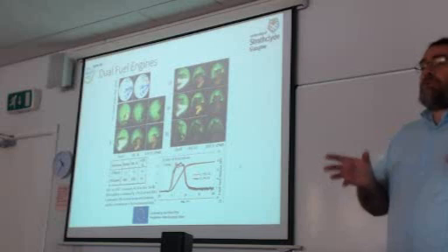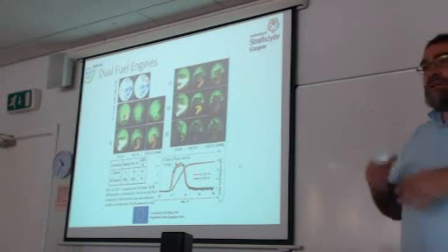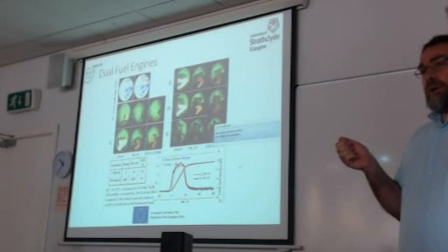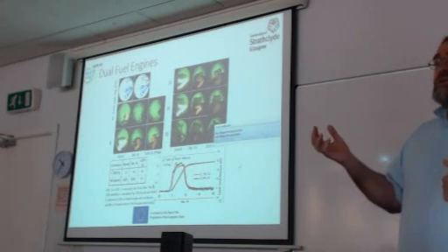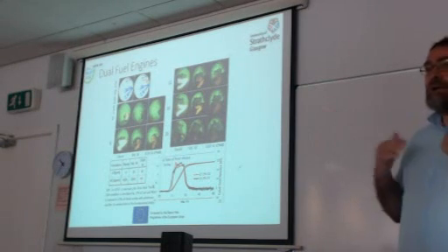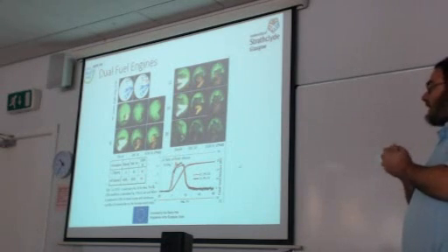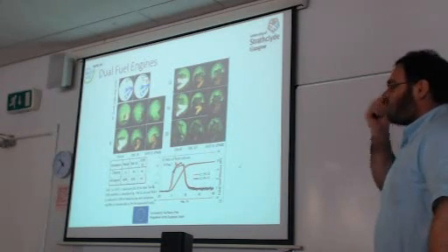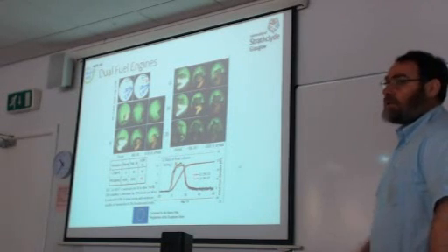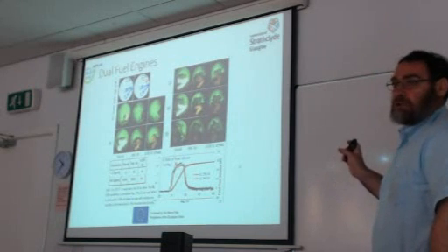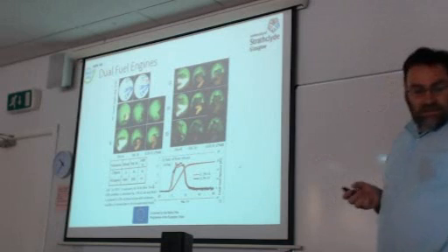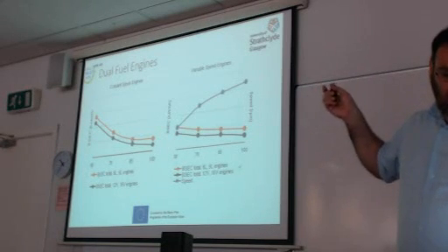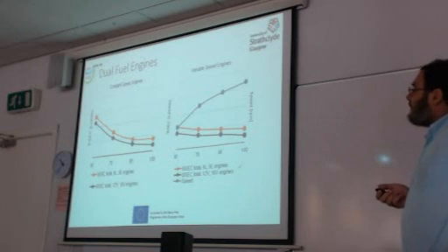No, it affects the efficiency as far as for operating EGR, the EGR system, energy needs to be consumed. Yeah, it affects slightly. Certainly, it affects hydrocarbon emissions and carbon monoxide. So, as I mentioned before, we have two different trends. Trying to increase efficiency and reduce CO2 will increase NOx. If we need to reduce NOx, then we will increase CO2 and decrease efficiency. So there are opposing trends, and yes, certainly there is some influence on the efficiency. But if I remember correctly, it's only 1 gram per kilowatt hour, something like that. It's not large, according to the manufacturers.